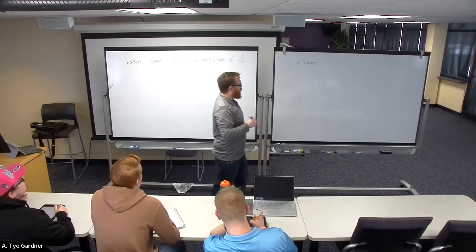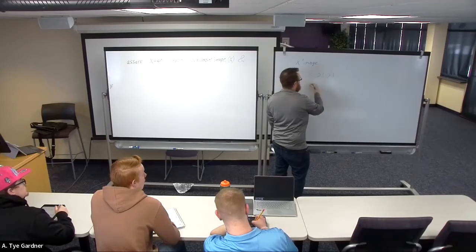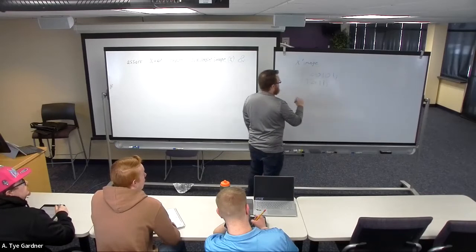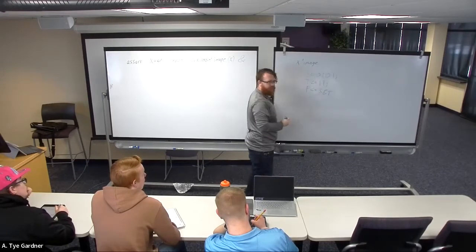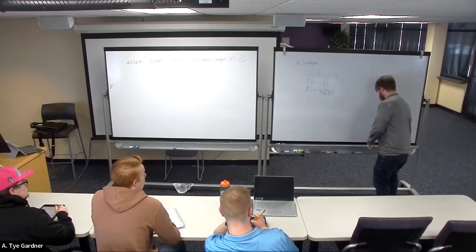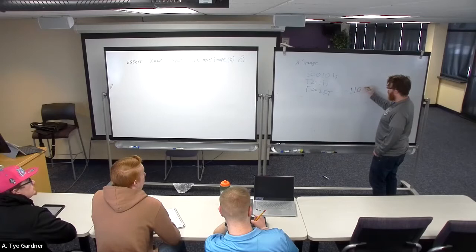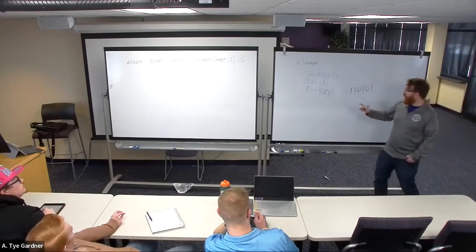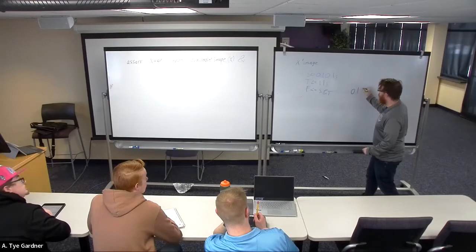The ampersand sign is just saying that if I have a standard logic vector S that is equal to 0, 1, 0, 1, and I have T that is 1, 1, then if I assign F to S ampersand T, all that does is it concatenates them or sticks them together such that F is now S and T. Sorry, S first, good catch. So 0, 1, 0, 1, 1, 1.